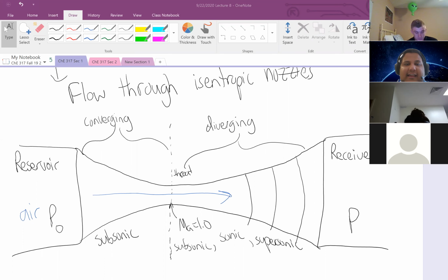It takes a properly designed nozzle with your pressure conditions at very particular set points to achieve that sonic and supersonic confined flow. Because in a typical flow through a pipe, there's nowhere for that wave to propagate. And so you're just going to end up with a truly confined flow, and you're going to run up against that mass flow rate issue.